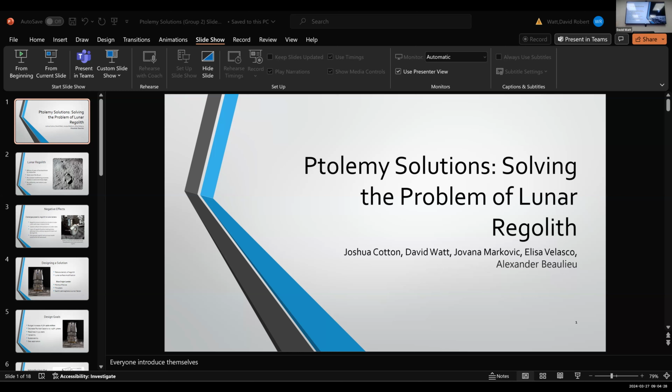And the size of the whole capsule, which we actually touched on earlier, with the railing is 1.66 meters high and about 0.61 by 0.61. The one individual tarp is roughly 10.5 by 10.5 meters with 9 millimeters of thickness. We did that calculation of 9 millimeters based on how much heat is being applied to the tarp. And